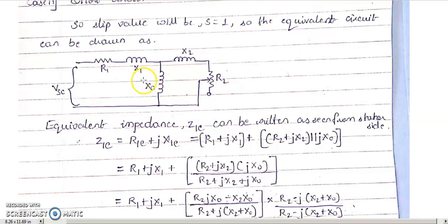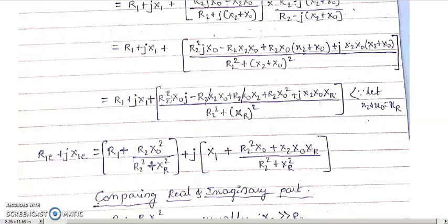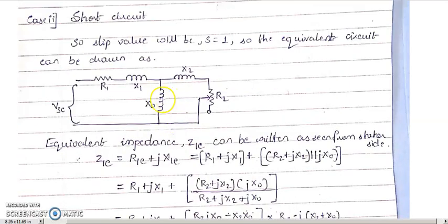So the drop will also be less. That's why I'm going to ignore R0. Only the X0 value is to be considered, because this is pronounced more when compared to that of R0. So the loss due to IC is less. So I'm ignoring R0, so it becomes open circuit, and only X0 will come into the picture. See, everything is approximate. It's not 100% correct. It's all approximation.